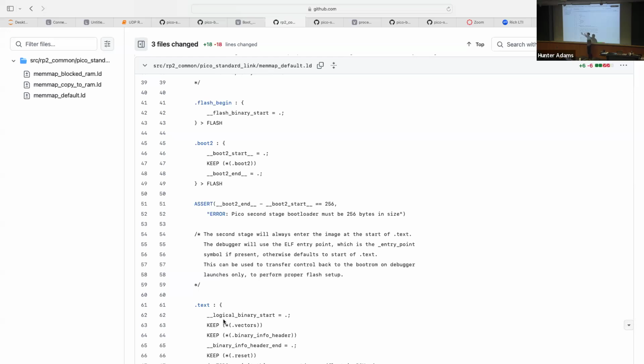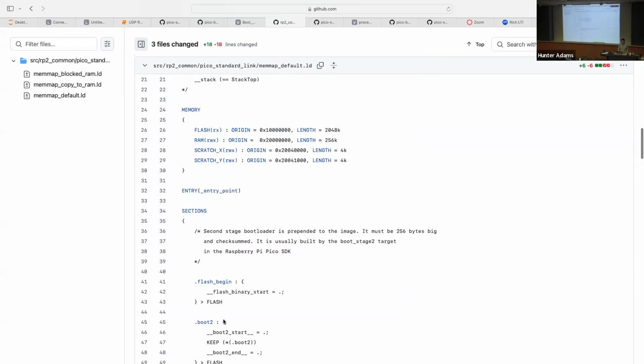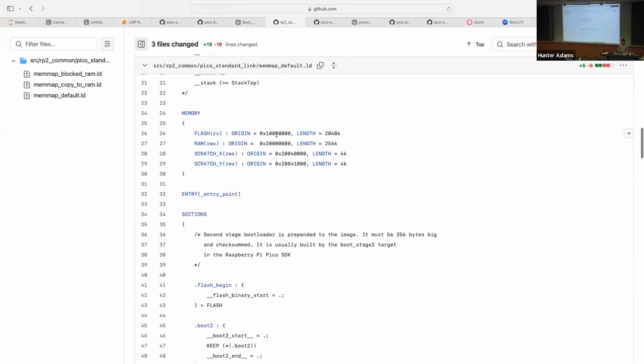I don't know, maybe it looks for data from some other kind of sensor, a serial input, Wi-Fi, whatever, right? You want to put a stage 3 bootloader there. But you want to compile a program for compatibility with that stage 3 bootloader. One thing you could do is change the linker script for the application code that you're compiling to be loaded with that stage 3 bootloader such that its base address for flash puts it above that bootloader. Right, so you have the freedom here to decide where this stuff goes.